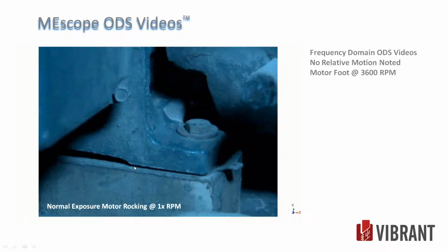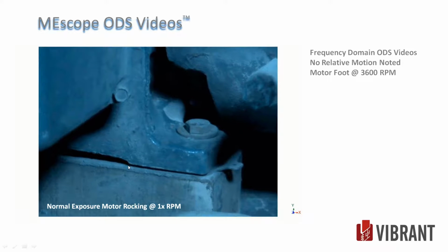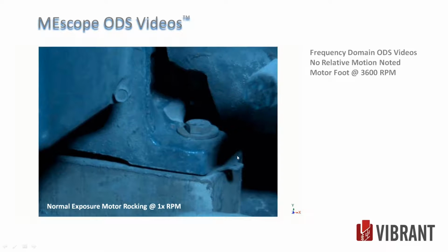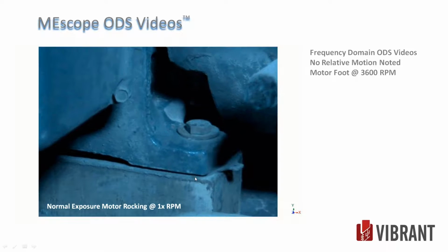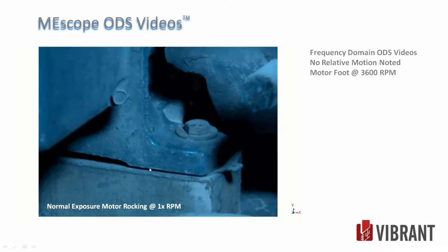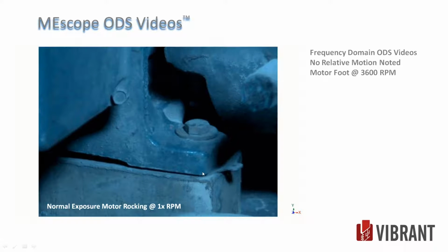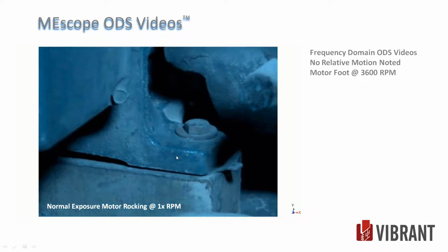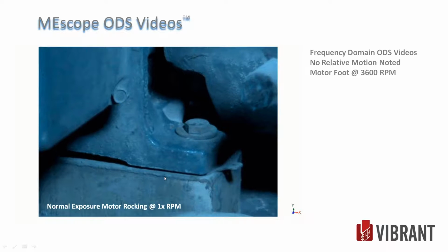What I was looking for was a loose bolt where this would be lifting somehow, or any change in this line of contact here. So there's a shim under there. It looks like a crack, but it's just a long shimmed interface. If there was looseness, this would be changing, and there's virtually nothing of a change here. The block's moving underneath, the spacer block, the foot's moving with it. The bolt seems to be tight and not pulling out.